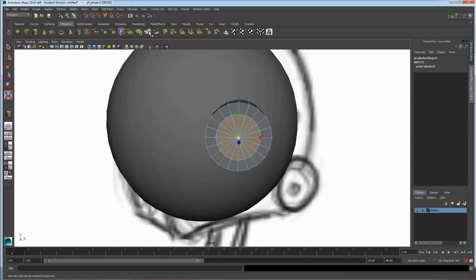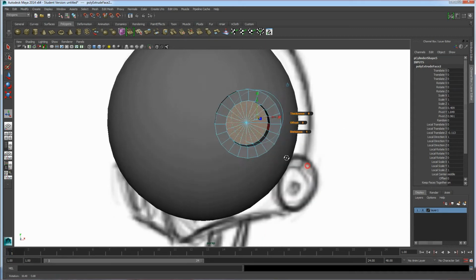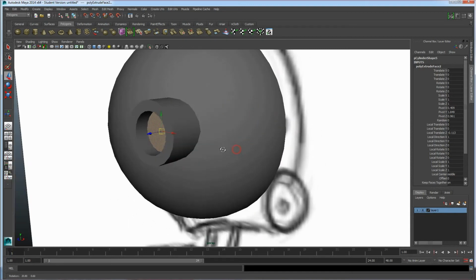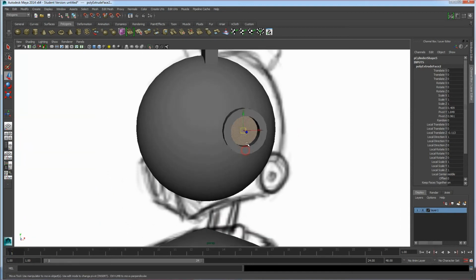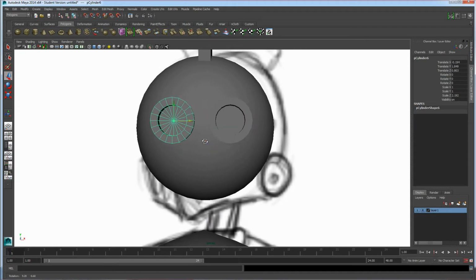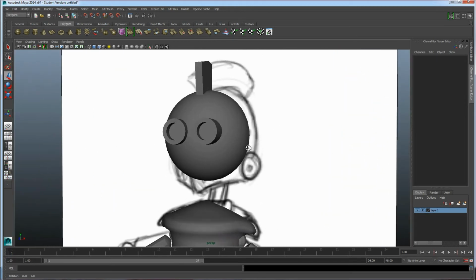I'm going to go to Extrude now, and grab the blue one, and pull that straight back. So now he has more of a shape to his eyes. So right click, Object Mode, and we have this. I'm going to take this object again, Control D to duplicate it, slide it directly over, and click off of it. So now I have two eyes on the character.